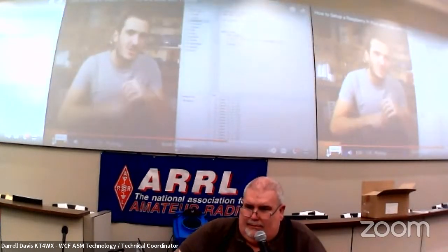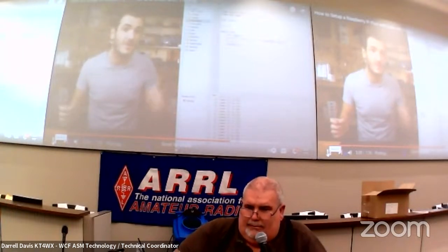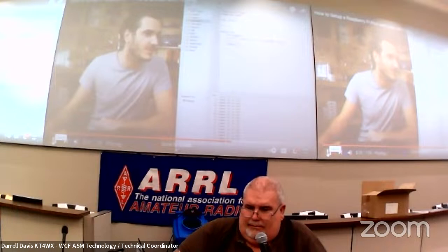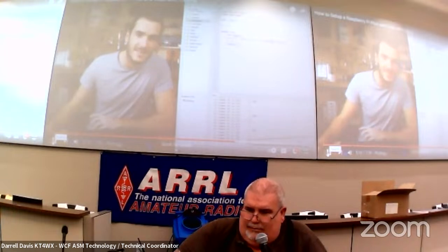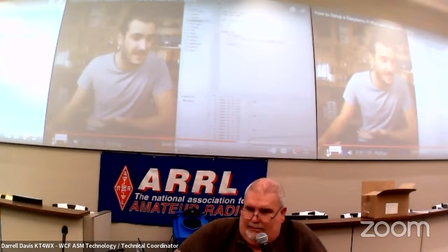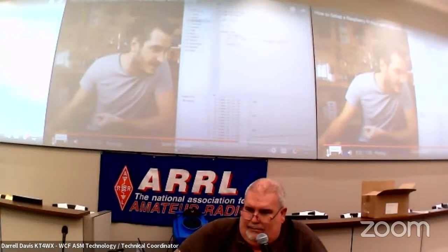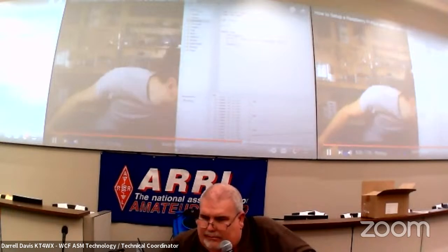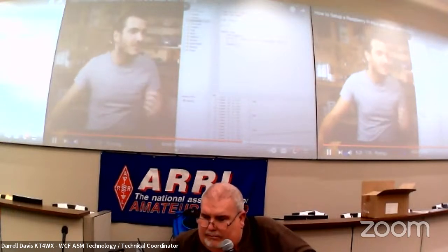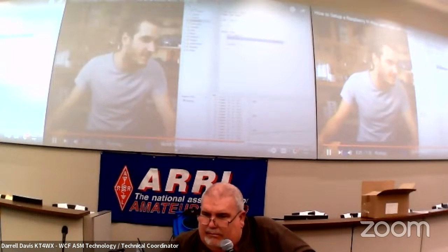So this is a neat way to print the values of variables to your console so you can see what's going on. There is a pretty cool feature as well, where if you go to View and Plotter, you actually get to see a plot of various things that are happening in the Pico. Down the bottom here, we have the key to see this. Blue times orange is red. So it's picked up on our print statement, and it's actually extracting information from it.